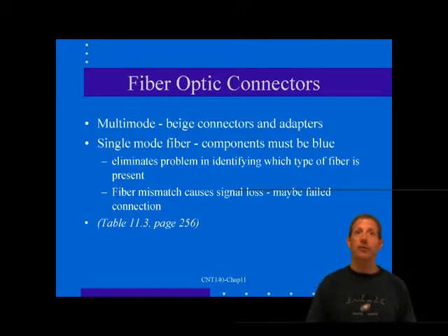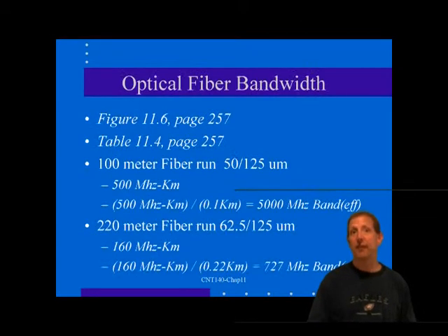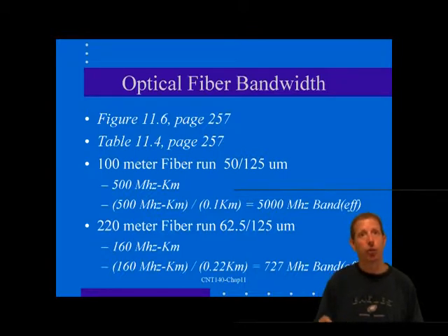Now, if we look at the optical fiber bandwidth, in multi-mode fiber, the most significant factor that limits the link distance is called optical bandwidth. And this term is a bit of a misnomer, as what is meant is the capacity for information transmission. As with many of the optical parameters, there are significant differences between the commonly used coax cable transmission terms and their corresponding optical lingo meanings.